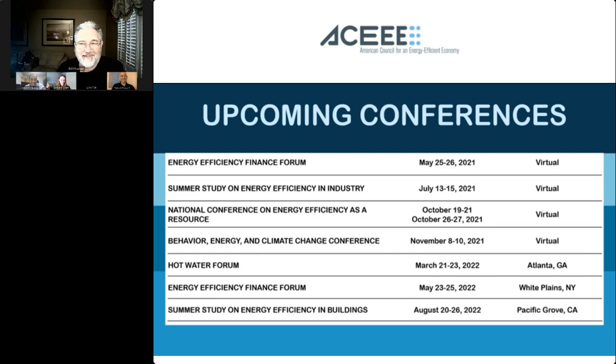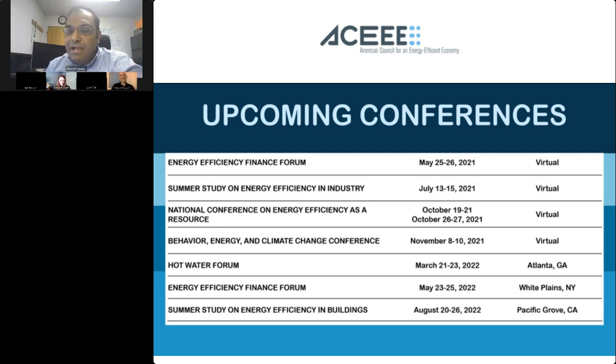Great. Well, we have actually looked at some salt hydrates, which can really fall well under the temperature range which is needed for the application. The reason we like salt hydrates is there are essentially 2 reasons. First, they have low cost compared to some of the other substitutes. And secondly, we don't have to worry about the flammability aspects, which is obviously an inherent characteristic of paraffins.